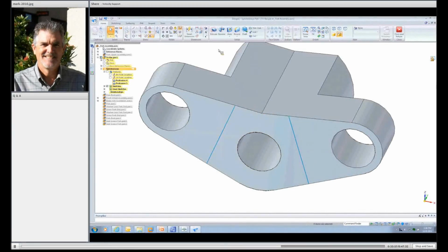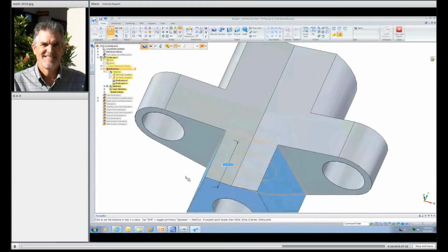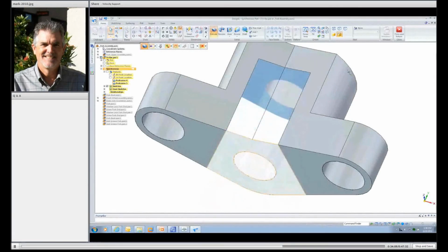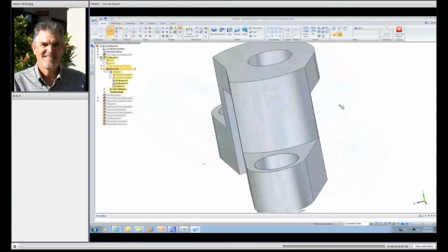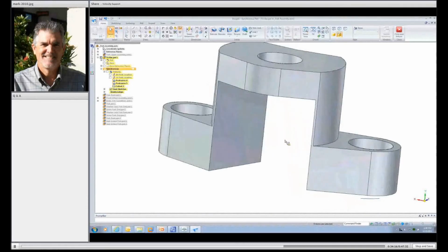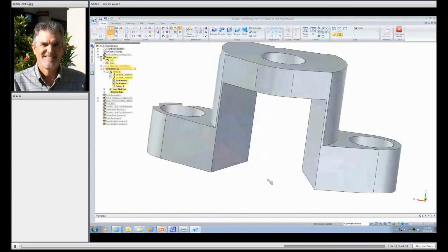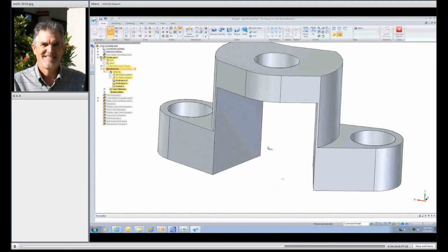And you'll notice that if I grab this steering wheel, both sides are going to adjust for me like I would want them to. But in this case, I'm going to move my steering wheel over to the edge, and I'm just going to rotate it out to add a little bit more meat to the model. So I easily rotated both faces out a little bit to give it a little more meat in the middle here. And then, if I grab this particular round on the outside face, you notice how I can easily modify this model. Because that hole was concentric to that round, it's all moving for me very easily.